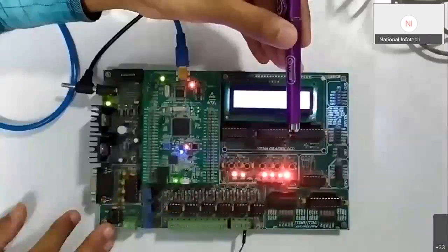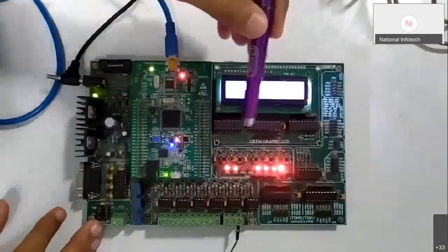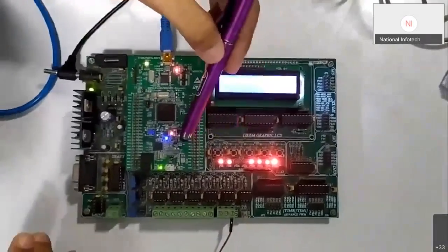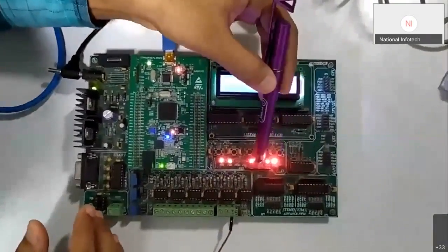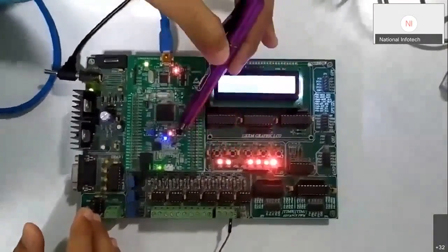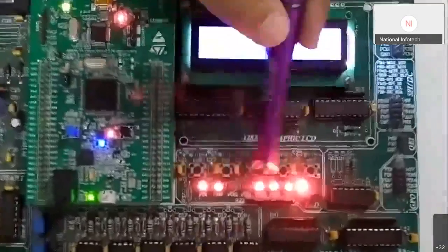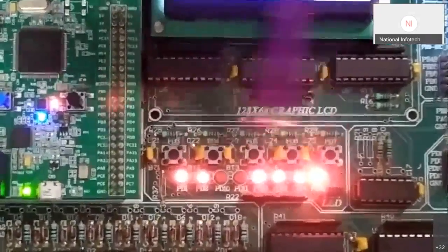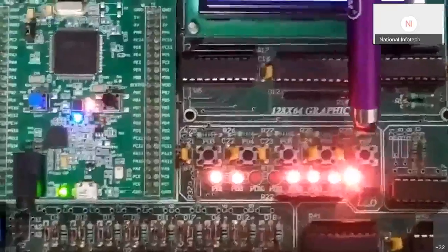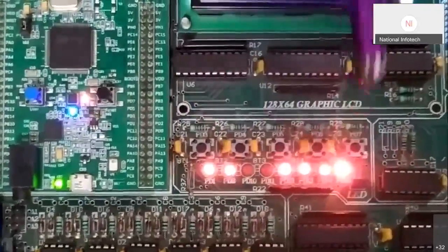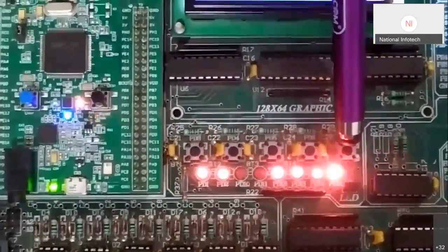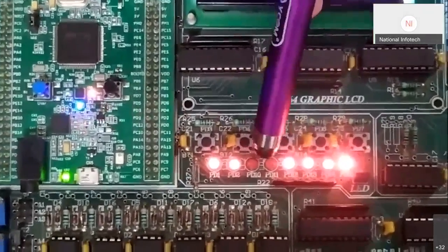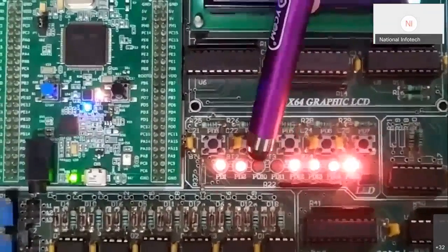Now we will go for the experiment. Here in the experimentation, this is the same kit for which we have already explained the different pin configurations and the controller. As we know, we have connected some LEDs with the D port of this controller, and the keys are connected with the E port. The LEDs are here and the keys are here. We have programmed the two keys, PD7 here and PD6 here, and the corresponding output we are observing at PD12 and PD13. This LED is PD12, and this LED is PD13.